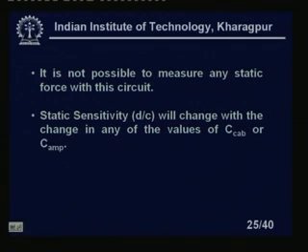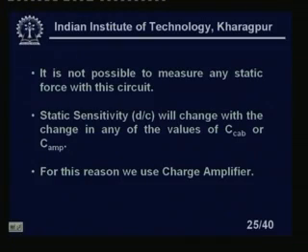Static sensitivity d by C will change with any change in the values of C_cable capacitance and C_amplifier. So, it is sensitive to these, so this must be constant. It is not possible to keep all these things constant, so it is better if we use a charge amplifier.